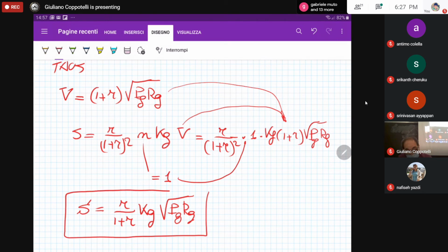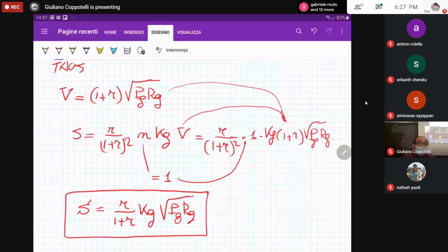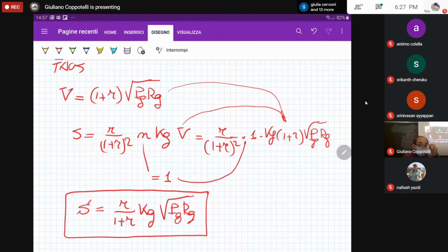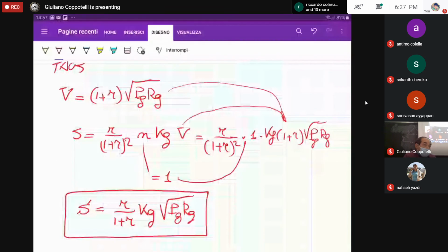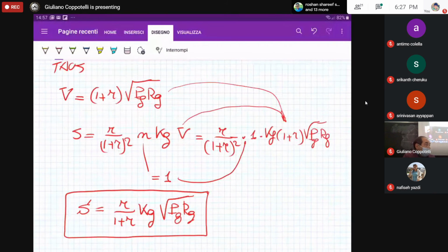That is the sensitivity that we can have when using your Wheatstone bridge with just one active leg, leg number 1, and by feeding this Wheatstone bridge with the maximum tension that is leading to the maximum dissipating power. So that is the maximum that we can have. We can't go further from the input tension point of view.